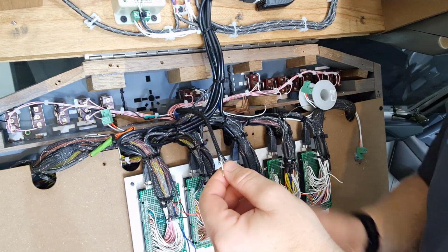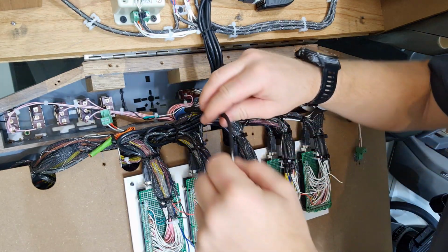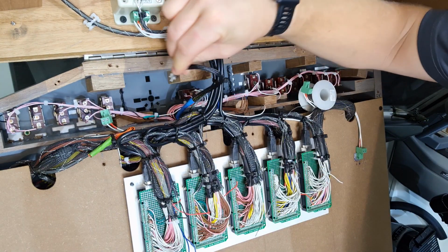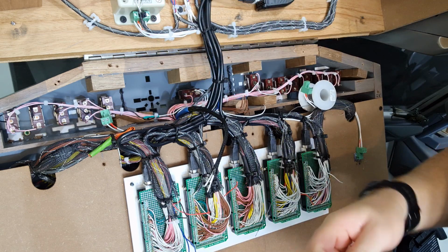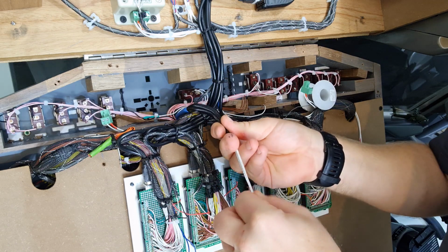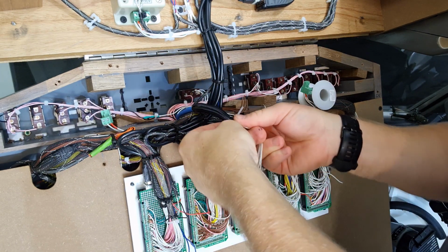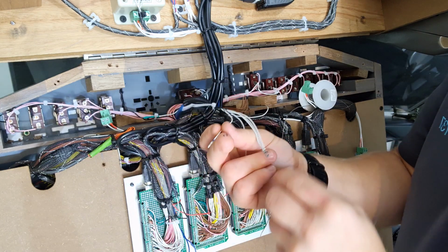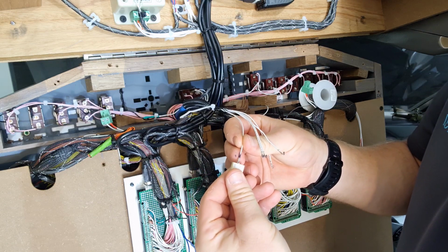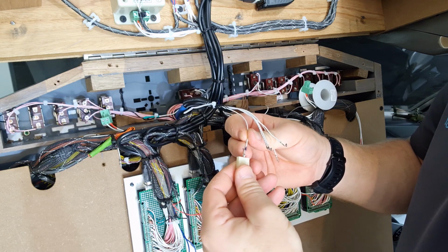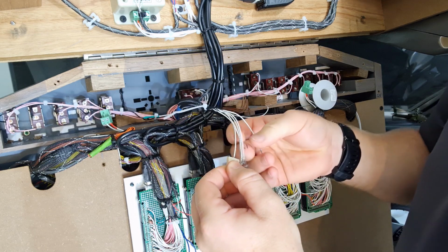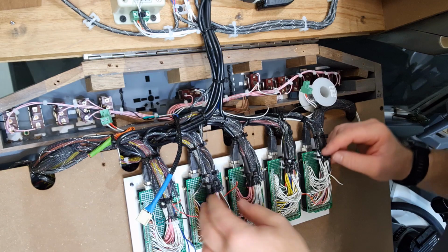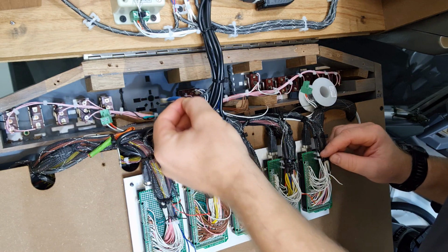So I've just put a bit of cable sheathing on, and that keeps the cables together and makes it look nice and smart when we connect it to the top of the rotary switch right there. So I can work on these ends. Hopefully just going to tie wrap this back a bit. Okay, and the only important one I need to know is that the black goes in the centre pin. And it doesn't matter about the other ones, they can go anywhere. And there's our first loom ready for the rotary switch to go straight in there.